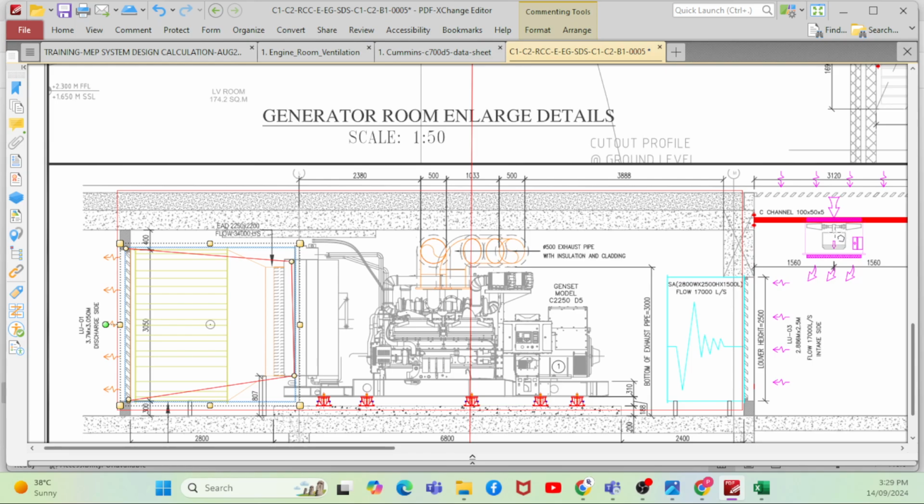For an external fan, you require static pressure and also airflow rate. This airflow rate will be the same as the intake airflow rate. And the pressure drop will be whatever you require to pump inside the generator room. So this particular sound alternator and this particular louver should be calculated and added to the generator external fan pressure drop, so that you are pumping the air into the room. Then, for example, if you are discharging and you require only 95 pascal, that is within the 127 pascal, so it can suck the air and discharge.